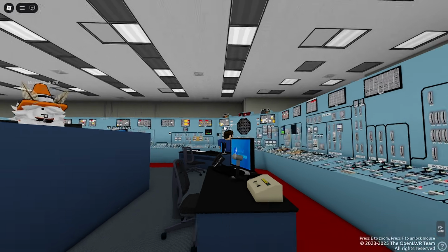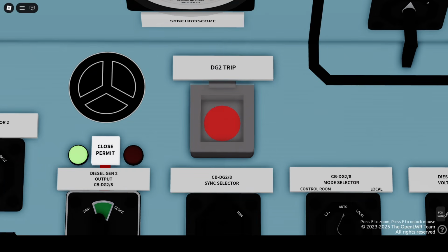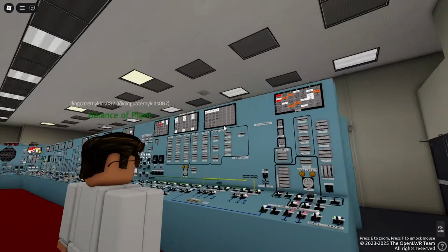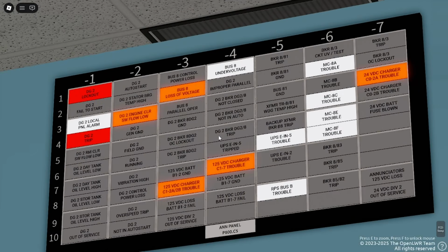Emergency trip DG2 on no service water flow, and contact Ops2 to investigate service water pump B switchgear trouble. That is correct. Service water is a system that cools down the diesel generators and residual heat remover heat exchangers. With diminished flow, the diesel generators can overheat.